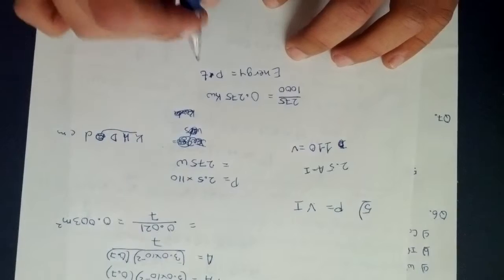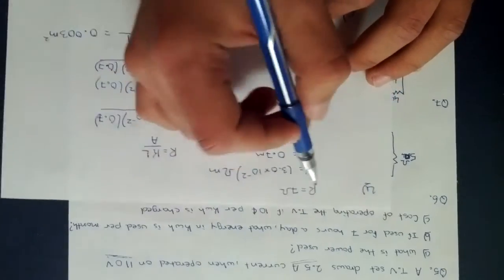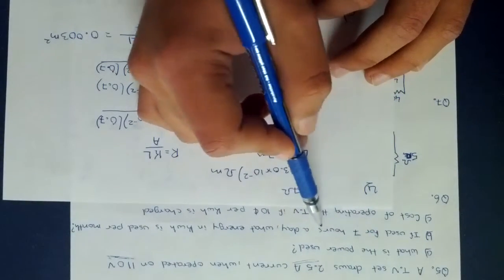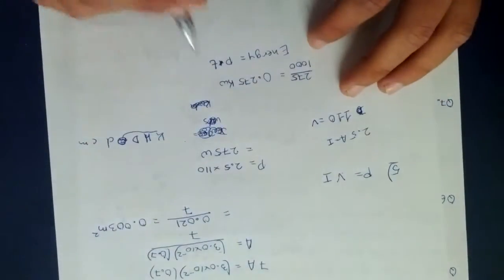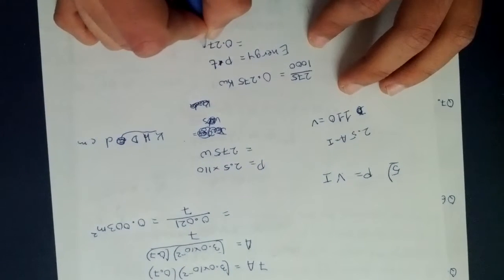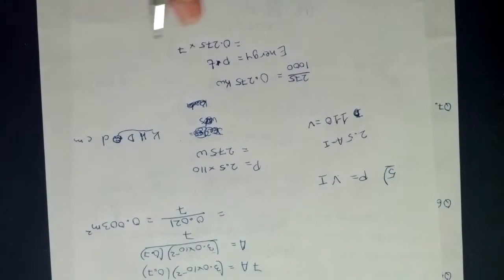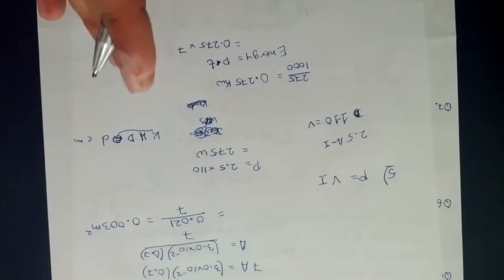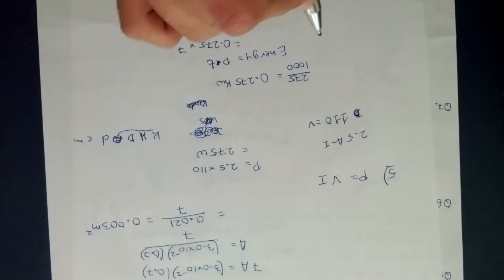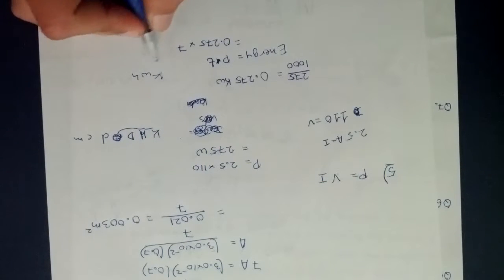Right? So what we need to do is convert the time. They gave us the time as 7 hours a day. So that would be power is 0.275 times 7. And yes, I did say earlier that we should have time in seconds, but in this case it's okay to leave it in hours because the answer should be in kilowatt-hours, kWh.